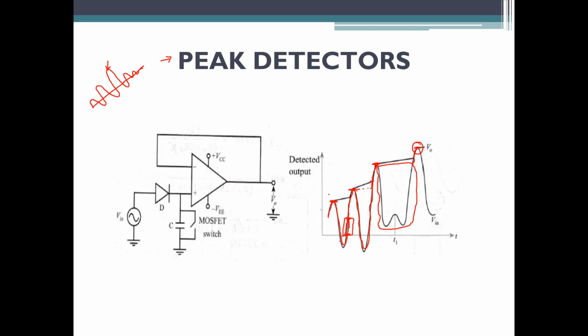This is what a peak detector circuit is. So if you apply multiple waveforms having multiple peak values, then the highest of all those peak values will be displayed at the output side, because you have a capacitor there, right? The capacitor will charge first to the lowest peak, after that to the second peak, after that to the third peak.